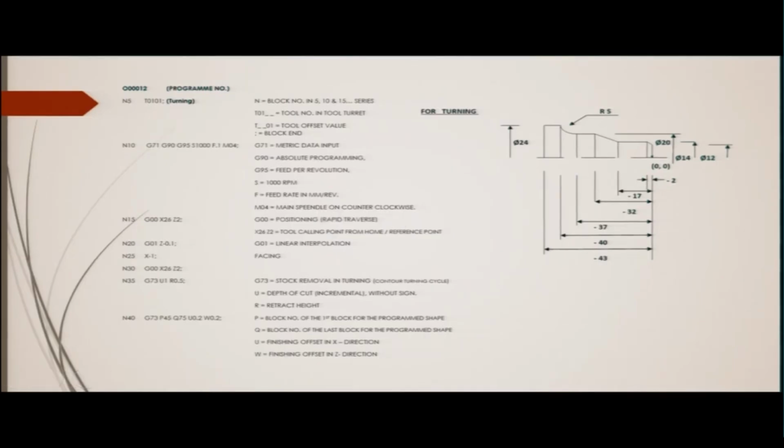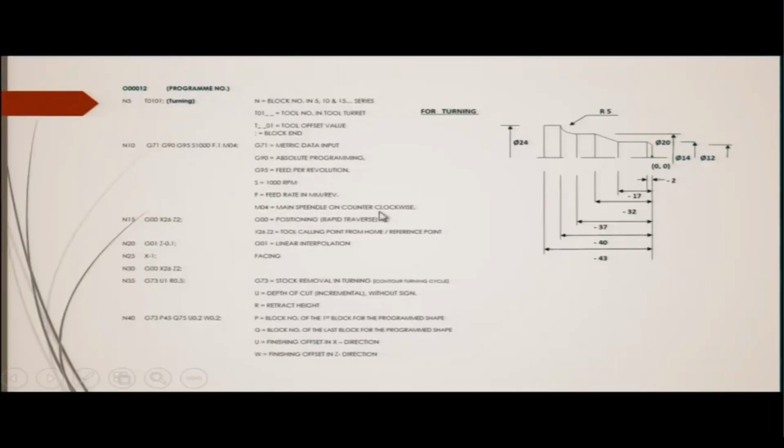So, in the table you can find out what is M01, what is M02, M03 for example in the clockwise direction, M04 is in the counterclockwise direction, and so on. So, each code tells the MCU that the hardware has to do something in a certain fashion, that is all.